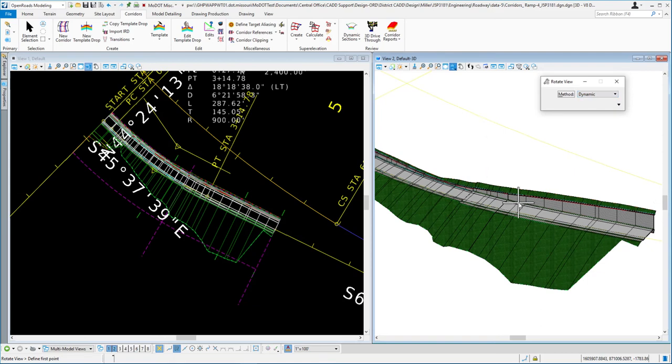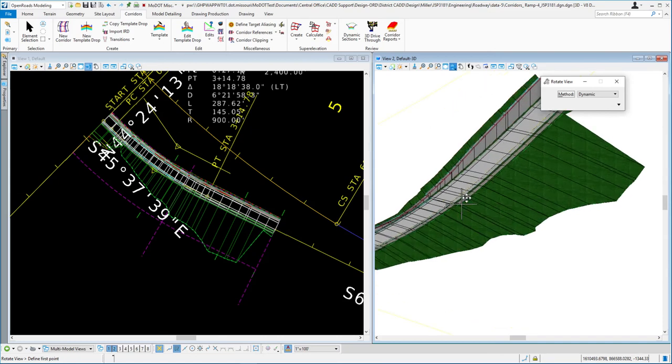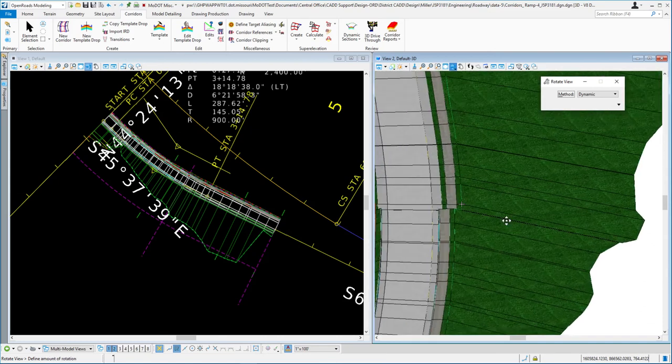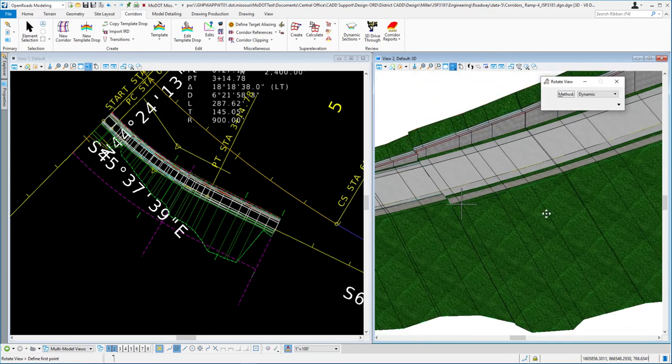But what you'll see happening is in the middle of your window, you'll get this crosshair. This crosshair is very, very important for you to be able to navigate around this window. What you want to do is snap it to a piece of element out there, and you'll know it snapped by seeing that heads-up display, the little gold X telling me I got a key point snap. Once you have that yellow X, you can let go of it. Of course, it didn't snap to it. Snap to it. There it goes. Now it's on there. If it's a big, thick crosshair, it didn't snap, and now it's a thin one. So now anywhere I select it, it's going to rotate about that pivot point. So I left-click and hold my mouse and just rotate around. And I can even zoom into that. And right there, you're seeing where we got curb and gutter going into our shoulders. And you see what's going on with the retaining wall over there?